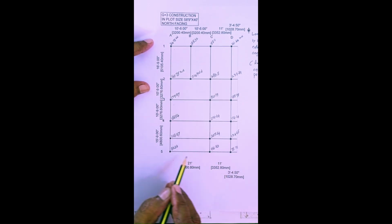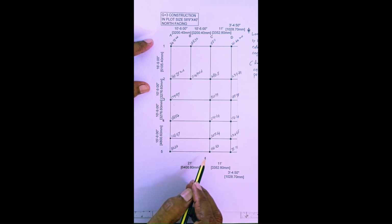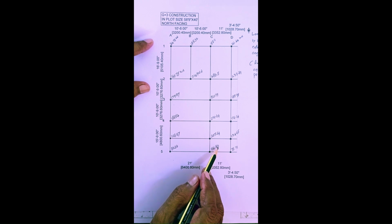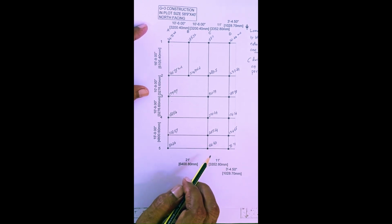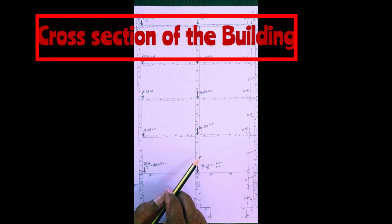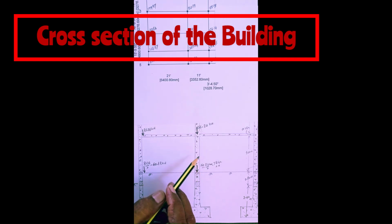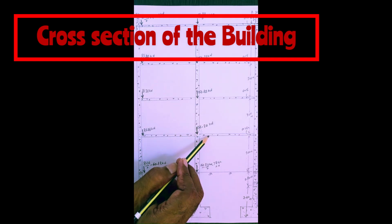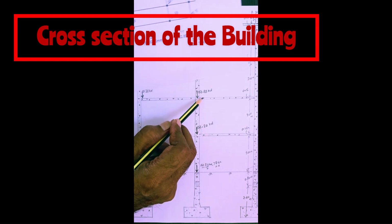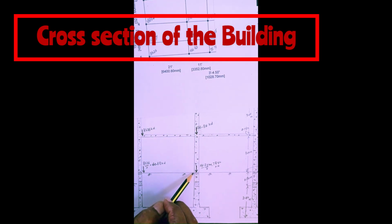For the first row of column, the end axial load is 81.36 and the middle load is 156.83 kilonewton. For this frame only, I have made a drawing like this. This load is 156.8 from the first floor, 156.8 from the second floor, the same from the third floor. Okay, what about the ground floor?